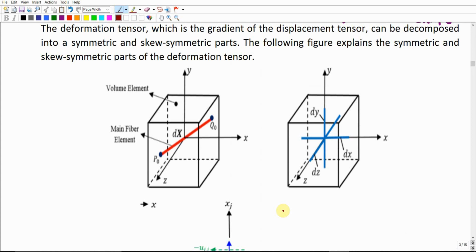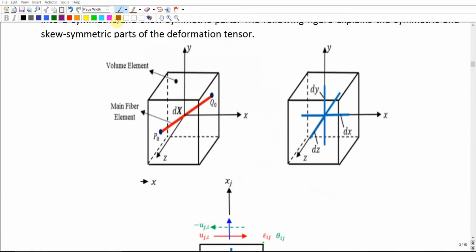This is also one of the things that had been covered in the mechanics of material class. According to the mechanics of material class, these 6 components can be represented over a cubic element like this one. So we're going to have here epsilon xx, going in the opposite direction from the other face, epsilon xx, and this is the normal strain parallel to x. This normal strain describes the changes in the dimensions of the continuum parallel to the x direction.